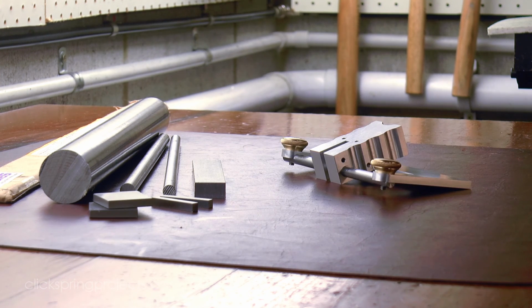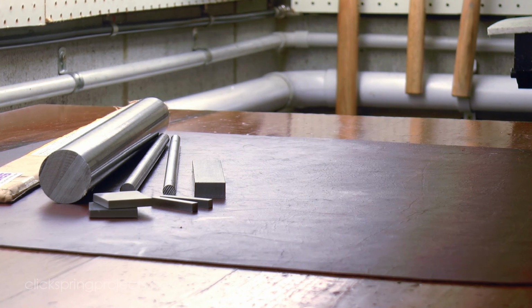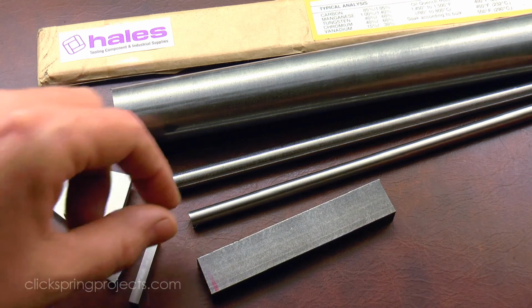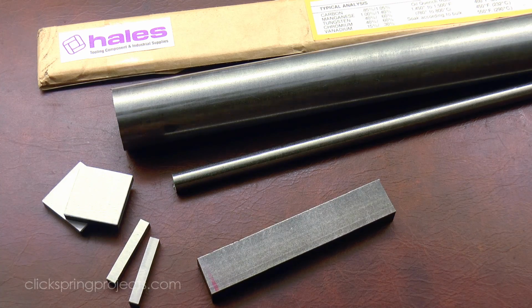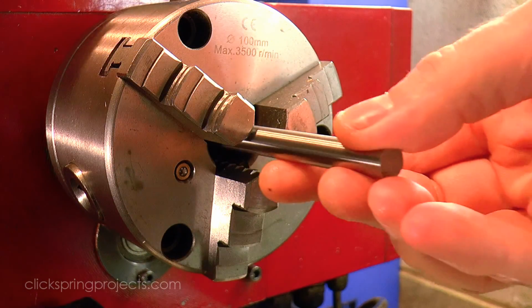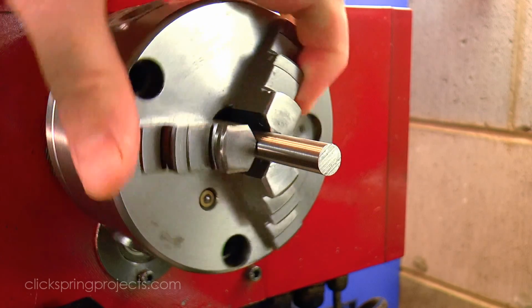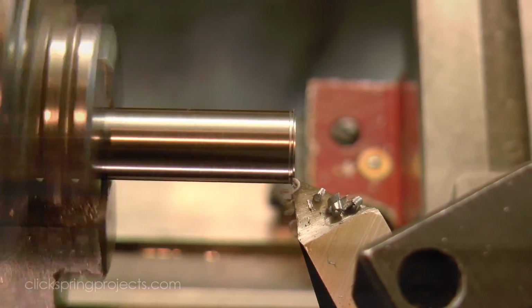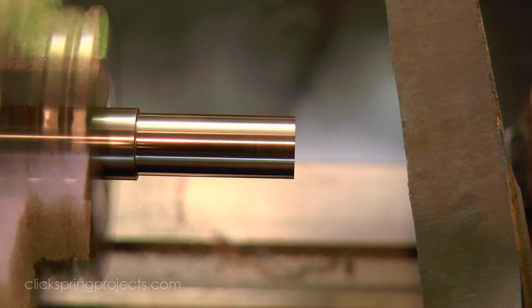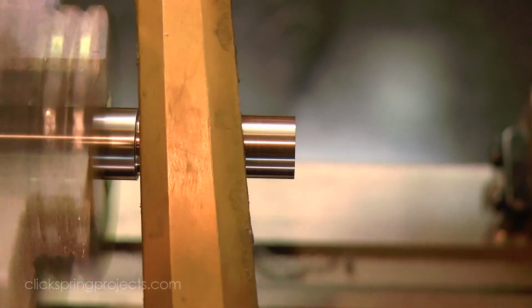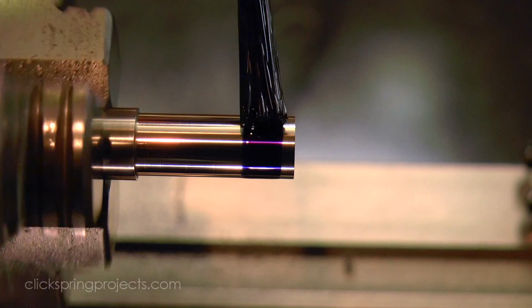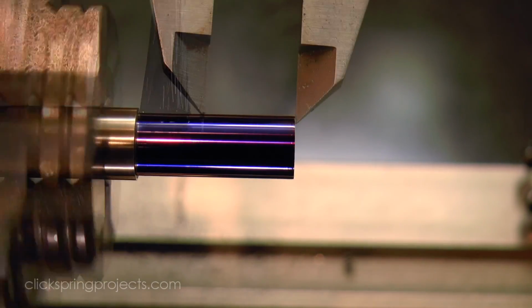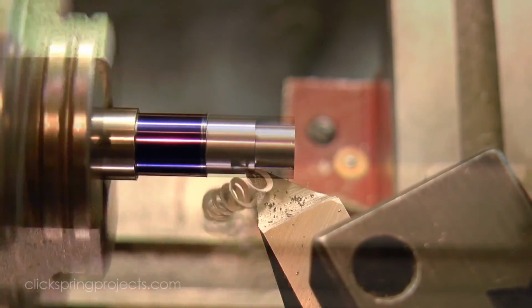Now the sharpening tool from the previous episode is a light duty hand tool, made from relatively soft materials like brass and mild steel. Our cutters, however, are going to have a much harder life, and so need to be made from a much tougher material. And there are several heat treatable steels that could fit the bill. But O1 tool steel tends to be the go-to candidate for this sort of job in the home shop. Like most of the high carbon steels, it's relatively easy to work in the annealed state, so we can form the delicate shapes that we need using common home shop tools. But its big plus is that it's so easy to heat treat using the standard home shop method. No special gear is required, just a propane torch and a bucket of oil.